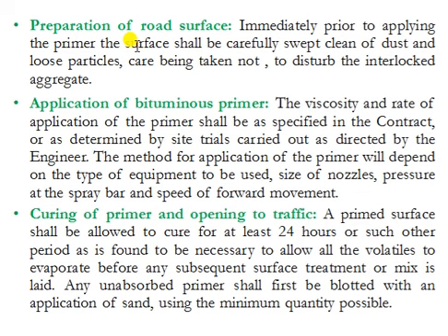So before spraying of the primer, the surface has to be cleaned. The surface has to be freed from dust particles. The surface has to be kept clean from other impurities, and the cleaning process should take place in such a way that we should not disturb the interlock aggregate. So care should be taken while cleaning the surface.